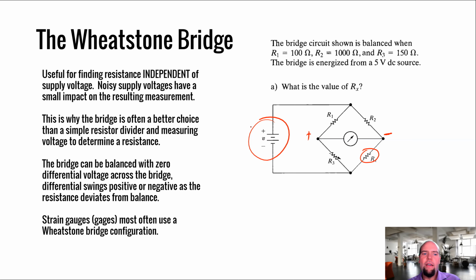So for instance, a strain gauge is a very common transducer. A strain gauge converts deflection into resistance. It converts mechanical deflection, so flexure, something flexing, into resistance, and it works pretty simply. It's kind of a membrane that has a resistive material on top, and when you bend that membrane, the resistive material stretches out, and that causes the little particles to separate, and the more they separate, the more their resistance goes up. So it's a fairly simple operation.